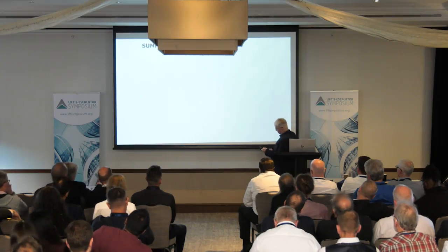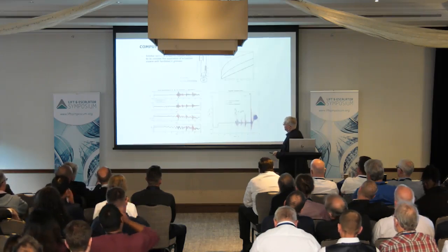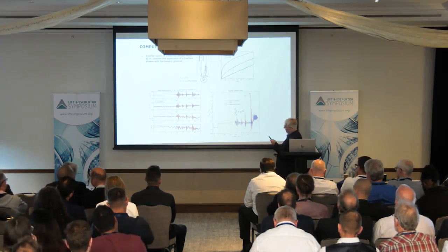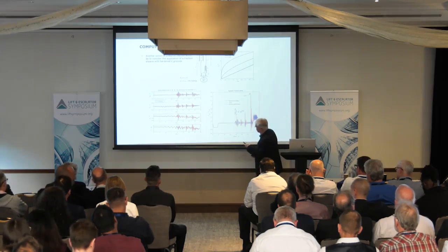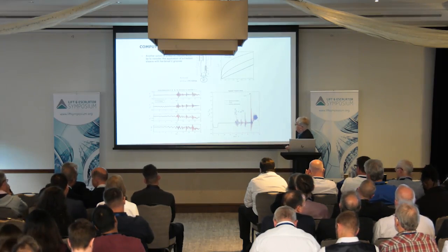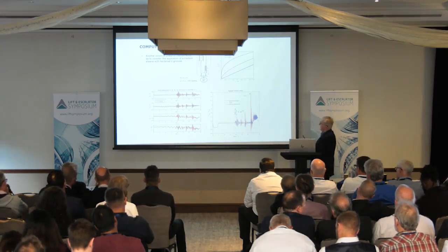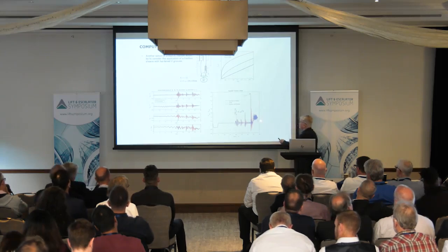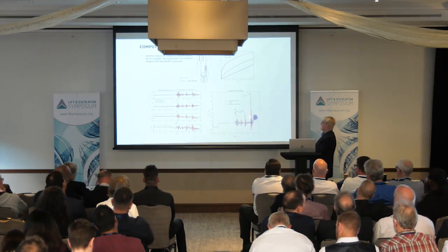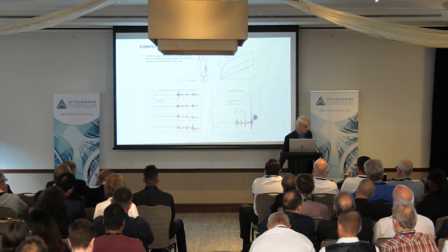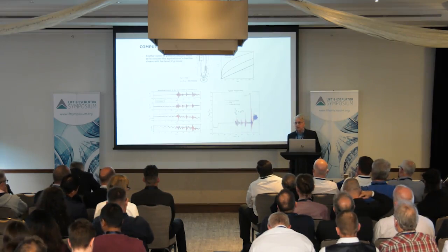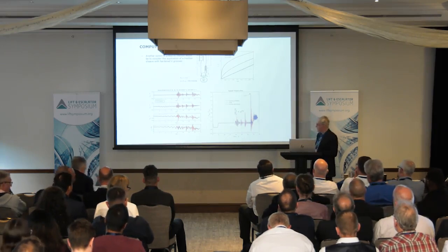So the red line is the previously calculated traction for vertical displacements of the masses, and now the blue line is after we apply the compensating sheave tie-down, and the applied traction ratios are in the blue line. We avoid these peaks here. So there's another option to take into account, and that's common again in situations where we apply tie-downs in high-rise buildings.